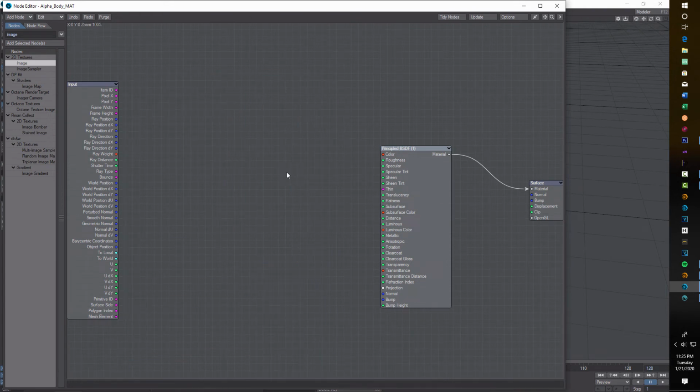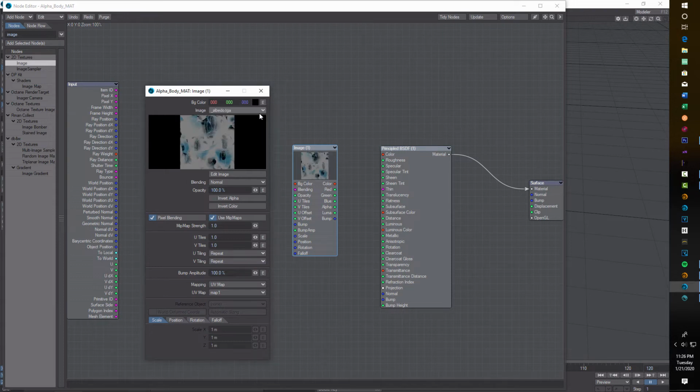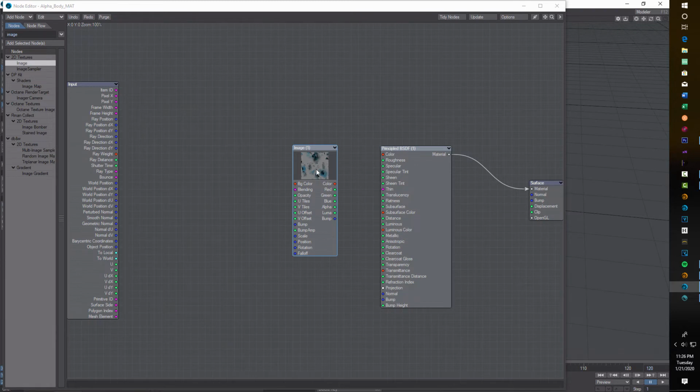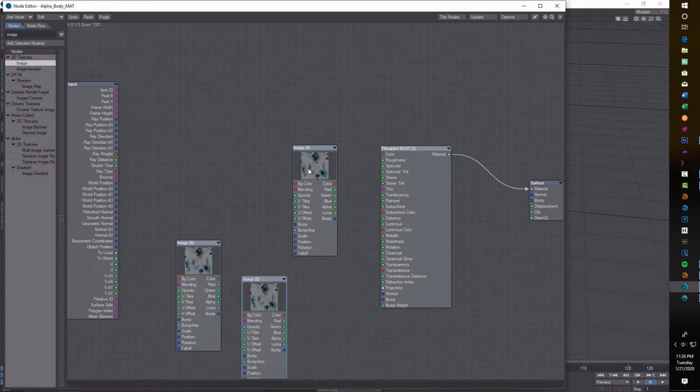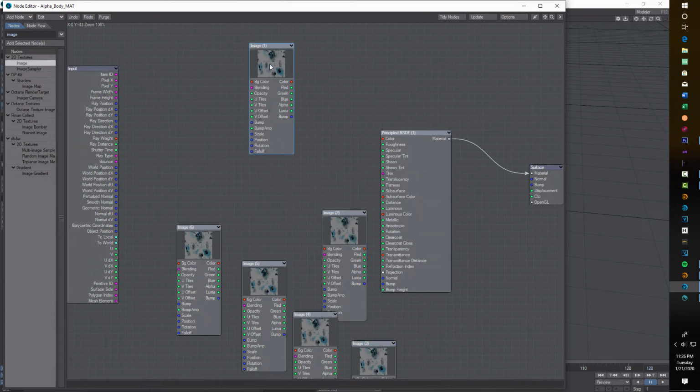You know, I didn't mean to do that. Let me start over. I'll go to Image, double click this, and before I copy it, I'll go ahead and set it to UV map. Okay, and now all our images should already be loaded. I'll just go albedo, which is our color, and then I can copy this and go Control V. I think I need 6 of them, I can't remember, 5 or 6. So I'll just pull these down for now.